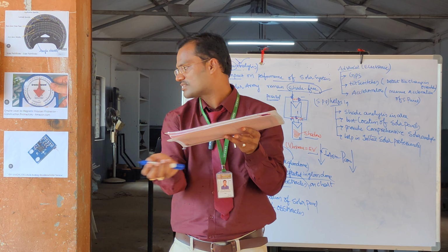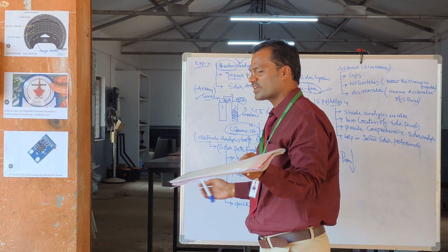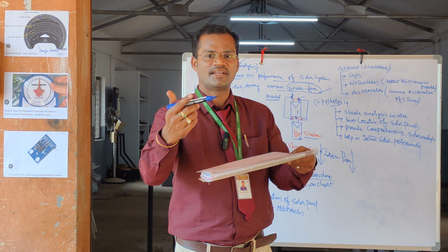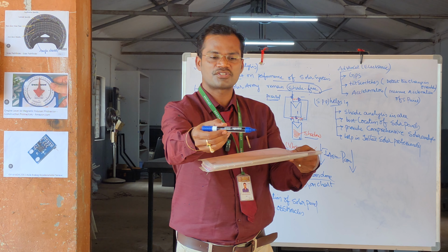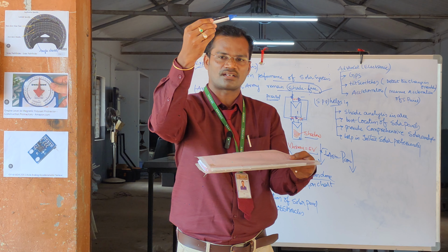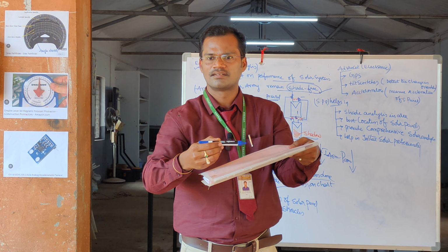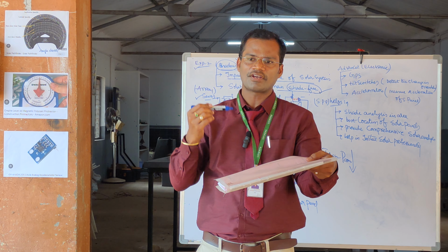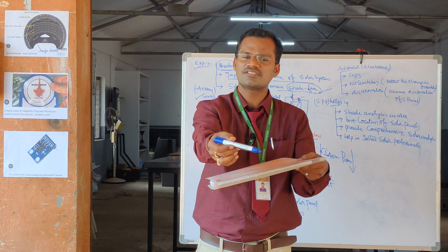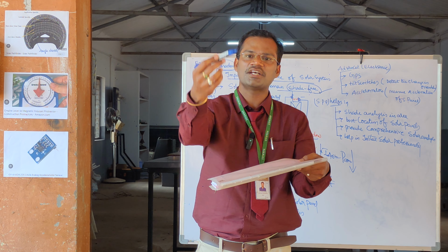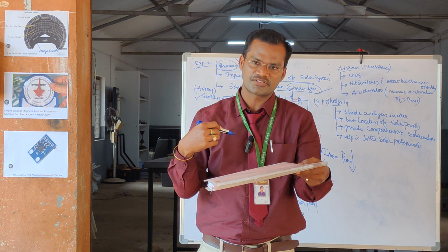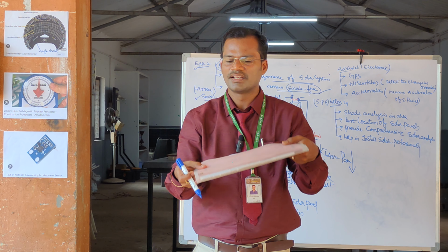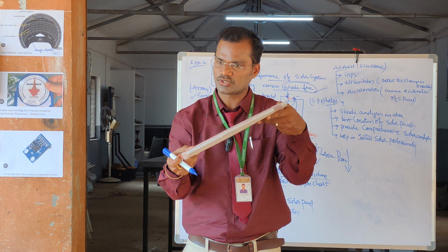Okay, so whenever you draw this diagram, it will show you the obstacle. So now solar is available, I mean you have the radiations from this side. Okay, so morning 6 o'clock, 8 o'clock, 1 o'clock. At 1 o'clock maximum energy is incident, and around 2 o'clock, 4 o'clock, 5 o'clock. You have to see that from morning 6 to evening 6, there should not be any obstacle in the solar radiation. No obstacle should obstruct the solar radiation falling on the panel in such a way that you have to mount your solar panels.